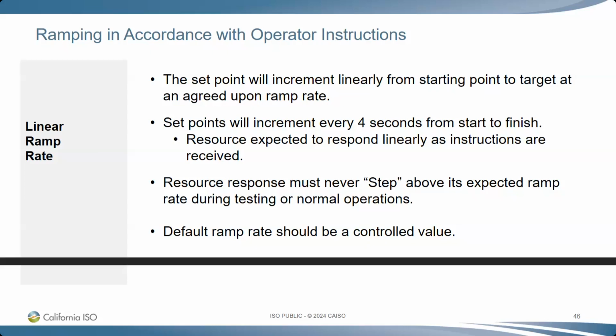Yeah, I can elaborate on that a little bit. So the linear ramp rate, as you know, you're receiving a 5-minute dispatch. We'll put this in 2 parts. One, you're bid in for energy, so you're receiving a 5-minute DOT dispatch instruction. Between the DOT, that 5-minute dispatch instruction, you have your DOPs, your dispatch operating points. So your 5-minute dispatch is calculated based on your ramp rates. Whatever your ramp rate is, it will dispatch you to those dispatch targets in a linear fashion.